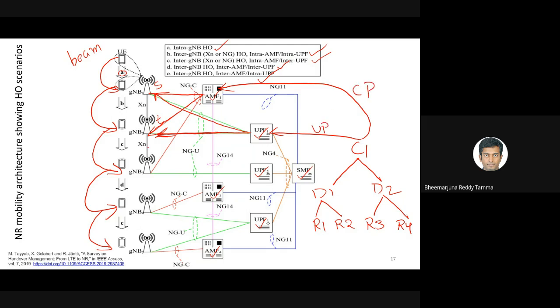So whatever I showed so far as a single unit here is blown up like this, where a base station is split into three components as RU, DU, and CU, where the DUs and CUs can be kept in the cloud or at the cell site, so that we can get the advantage of centralization, because we can reduce the cooling cost and we can also reduce the maintenance cost because we have fewer active components to maintain.